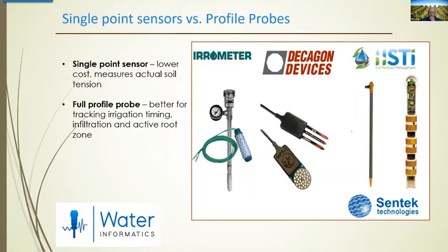That was the interface for gathering that data. But it's interesting to look at that probe because you can see the high and low bands, the gold there. And that's how the soil reads. It basically sends a loop through those two sensors, those two brass plates. And that's how it looks at the speed as it goes through the soil to tell you how much soil moisture you have.